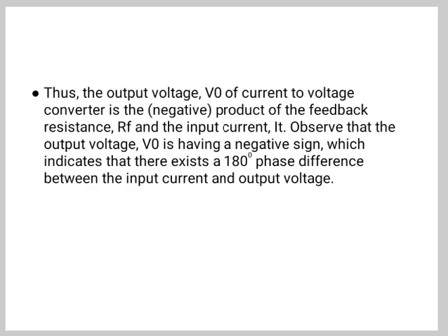One example of such an application is using a photodiode sensor to measure light intensity. The output of the photodiode sensor is current, which changes proportionally to the light intensity, and another advantage of the op-amp circuit is that the voltage across the photodiode, that is the current source, is kept constant at 0 volt.